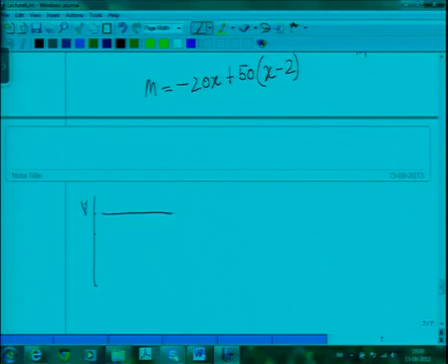Shear force will start from minus 20, at 2 it will jump to plus 30, and this is the distance 4. What happens at 4? We will see. At 2 there is no unique value, there is a jump, a step, a discontinuity in the shear force. At 2 minus, the shear force is minus 20, at 2 plus, the shear force is plus 30. So, it is a discontinuity, it is a step function, a discontinuous function.